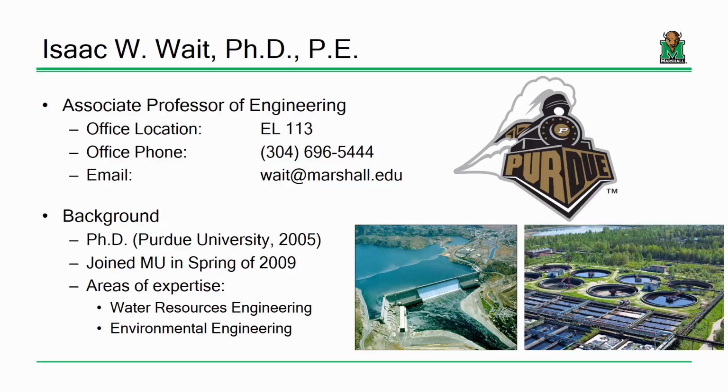The other image, anybody know what this is that we're looking at here? It's an aerial photo, but what is it? Hint, it's not swimming pools. Exactly, it's a water treatment plant. The circular pools are clarifiers, and you can see that the water appears to be very glassy and calm in those clarifiers because the point of those is for particles in water to be settling downward.